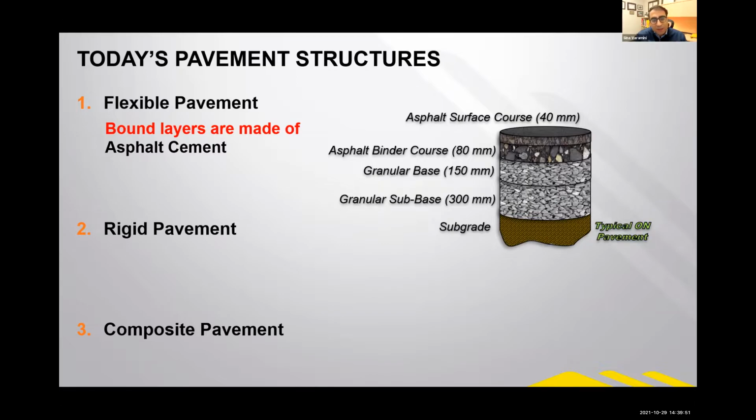They are placed on top of the granular materials to provide drainage, basically ensuring that if this structure gets saturated at some point, it would not be detrimental to the adequacy of the structure. So it does allow for the water to drain out. And then we have the subgrade, which is the engineered basic foundation for the on-ground structure.